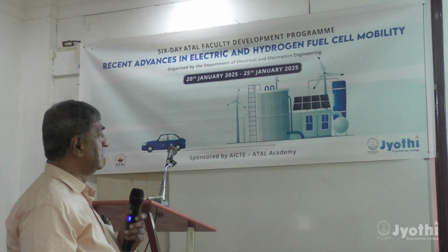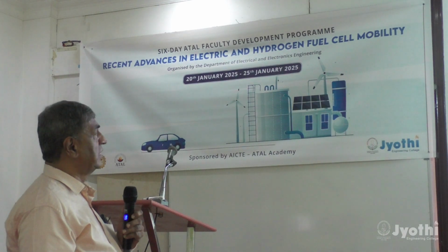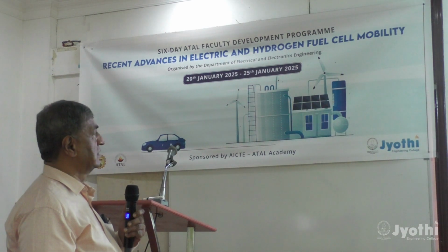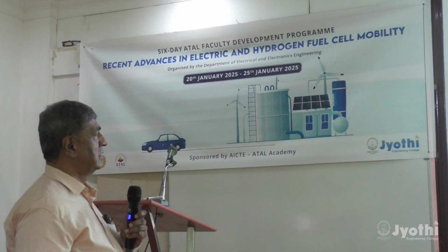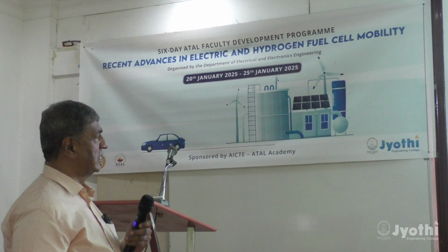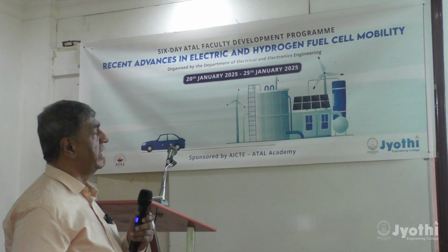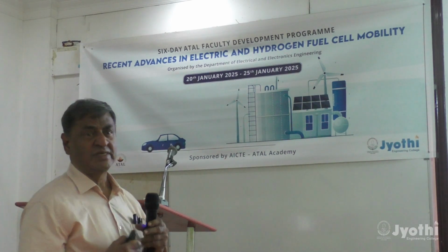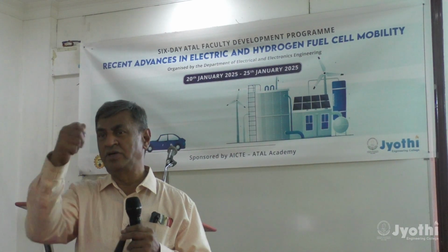Earlier, before heat treatment, the hydrogen evolution reaction was not happening. But after the heat treatment, the changes that happened in the microstructure really helped in both the oxygen as well as the hydrogen evolution. And so, using this cyclic voltammetry technique, we are able to understand the rate at which it is happening, both in the forward as well as reverse direction. And the stability test showed that even after one full day, still it had good activity. There was no change. Normally, what happens is that if you keep on using any sample cyclically, even mechanically, you are loading, unloading.